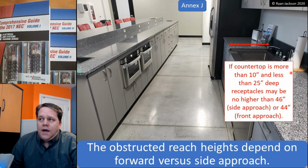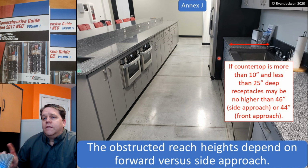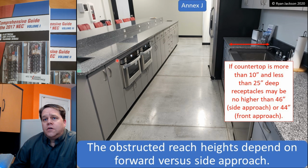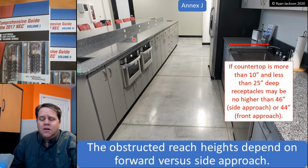So looking at this photograph here, the obstructed reach depends on forward versus side approach. So we would do what? We would measure the countertop, and we would also figure out if you can do a frontal approach or a side approach. In this, I believe we could probably do either in most of these areas. Side approach is probably the most comfortable. But it's also important to know that the height of this countertop in and of itself is regulated. 36 inches is the highest that the countertop could be. And therefore your receptacles tend to kind of take care of themselves. You know what I mean? It's not like you're going to have it 1.5 feet higher than the countertop.